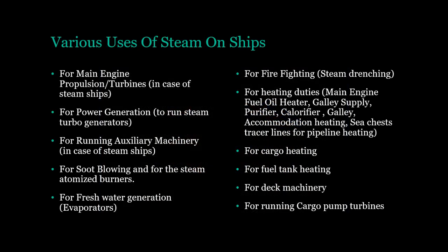Various uses of steam on ships. For main engine propulsion or turbines, in case of steam ships, for power generation, to run steam turbo generators, for running auxiliary machinery, in case of steam ships, for soot blowing, and for the steam atomized burners.